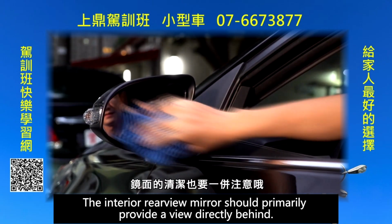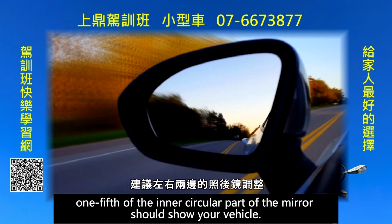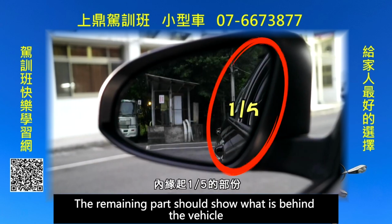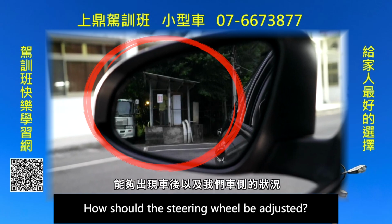The interior rearview mirror should primarily provide a view directly behind. It is recommended that in adjusting the side rearview mirrors, 1/5 of the inner circular part of the mirror should show your vehicle. The remaining part should show what is behind the vehicle and the status on the side of the vehicle. Teacher, I have one last question. How should the steering wheel be adjusted?